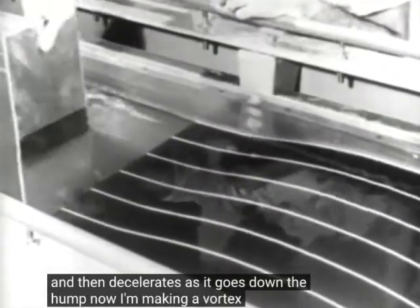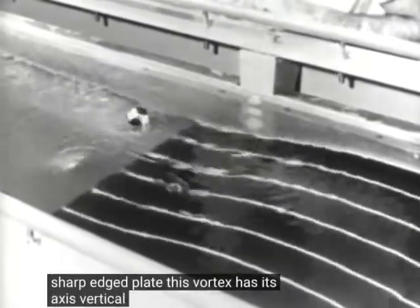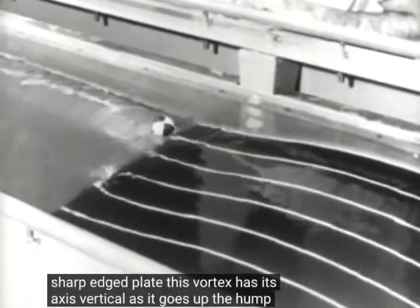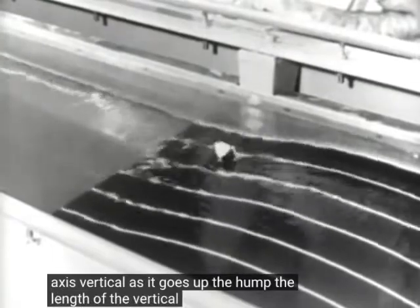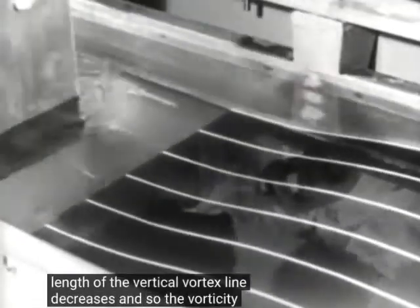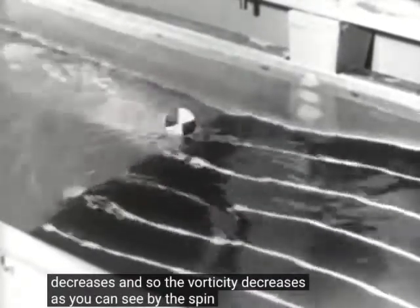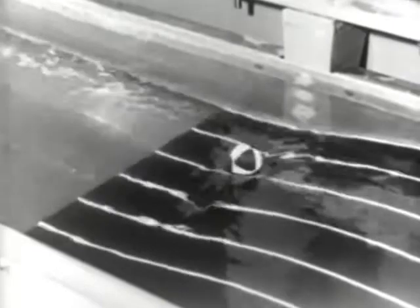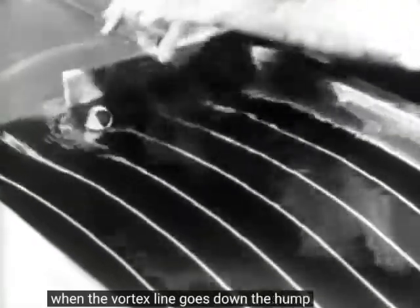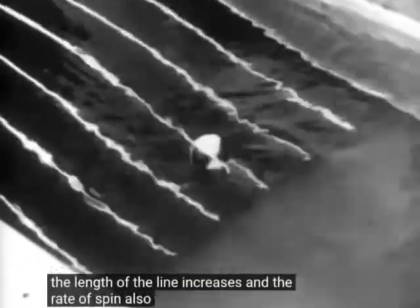Now I'm making a vortex with a sharp-edged plate. This vortex has its axis vertical. As it goes up the hump, the length of the vertical vortex line decreases, and so the vorticity decreases, as you can see by the spin. When the vortex line goes down the hump, the length of the line increases, and the rate of spin also increases.